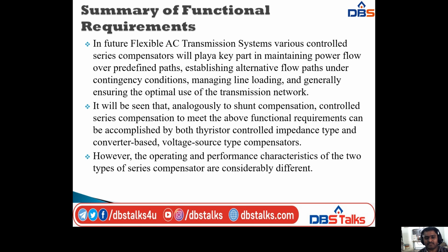It will be seen that, analogously to shunt compensation, controlled series compensation to meet the above functional requirements can be accomplished by both thyristor controlled impedance type and converter based voltage source type compensators. In the previous shunt compensation, we discussed the TCR, TSC concept, the thyristor switched and thyristor controlled concept.